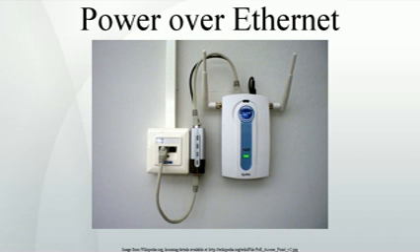PSE powers up PD. PD sends to PSE, I'm a PD, max power equals X, max power requested equals X. PSE sends to PD, I'm a PSE, max power allowed equals X. PD may now use the amount of power as specified by the PSE.